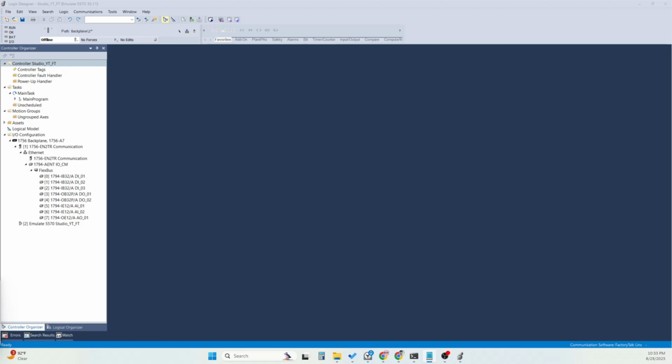Link it to a PLC tag and color animation so your button changes color depending on state. What you have to do first in Studio 5000 Logix Designer is create a bool tag. So how can you create a bool tag?